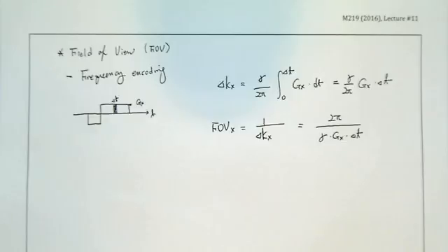Right. You have two choices. One, changing the gradient amplitude to be higher or lower. Lower means the field of view will go up, right? Or what? Lower the delta t. Delta t is the sampling rate, right? So either you reduce the sampling rate or lower the gradient. Which one is better? I don't know. Does Dan cover the SNR?